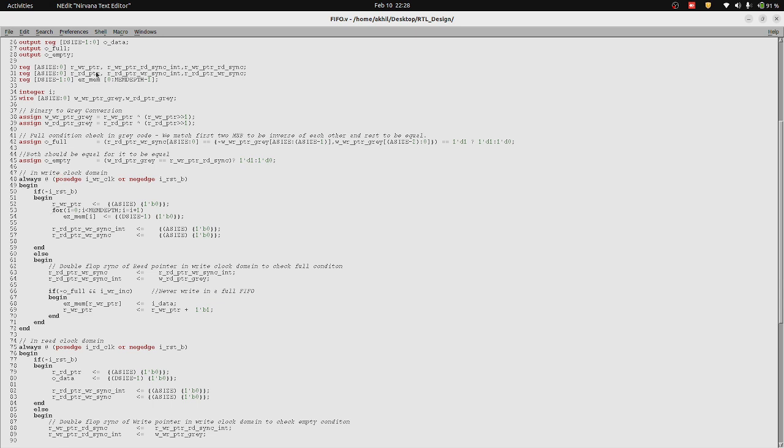Now this is the memory, the SRAM which we saw in the picture. This is the memory which we have declared. Over here you can see, we don't need to actually fetch 0 at reset. We can just have X over there, because I feel like this is extra hardware, but we can have it. Whenever FIFO is full we don't need to write, and whenever write is incremented we will write it, and obviously we will increment the write pointer.